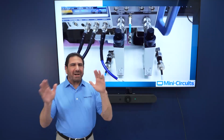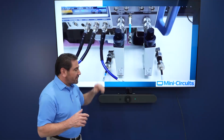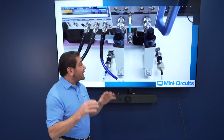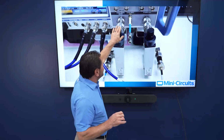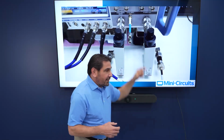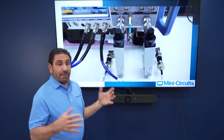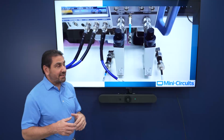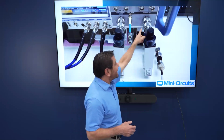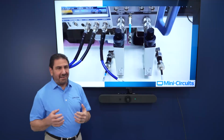You get easily a 20 dB dynamic range by using the 11 position attenuator with the fixed pad. This is 1 dB step. That's going to control the input power into the DUT. What's very important is when you're doing this and selecting a power to be outputted from the analyzer, you do a through path calibration. You replace the DUT with a through. You set this, for example, the maximum is what we start with, and in this case, it's plus 13 dBm. And we look at what comes back out. We configure the attenuators so that what comes back into the analyzer is approximately what we'd expect out of the DUT. We'd like about plus 10 dBm or so.